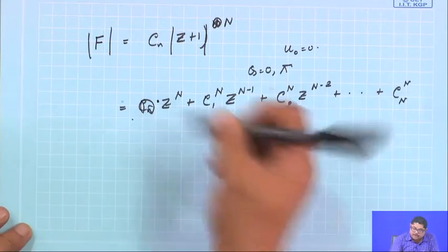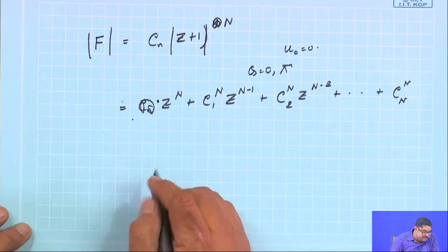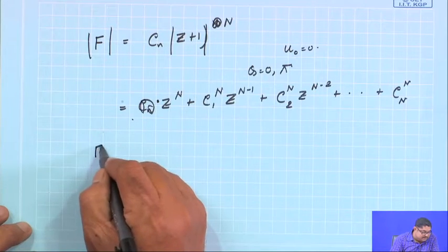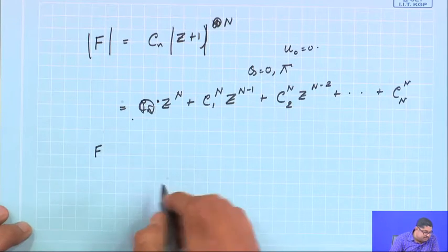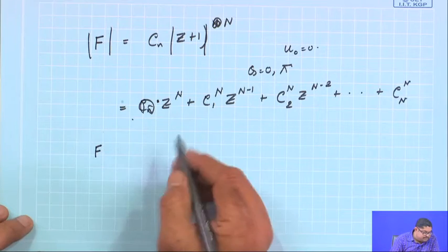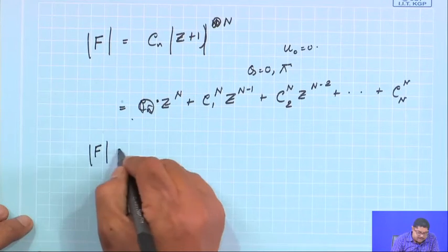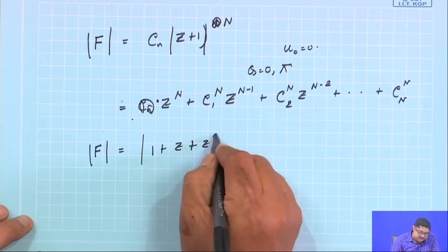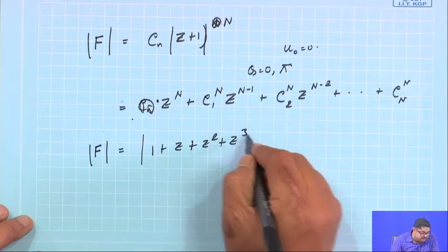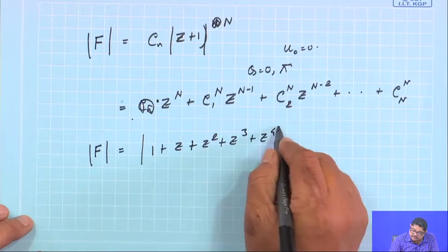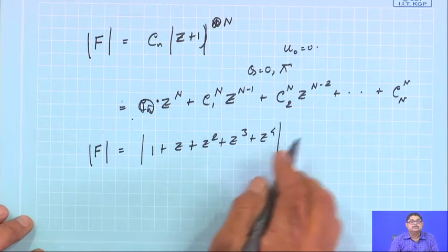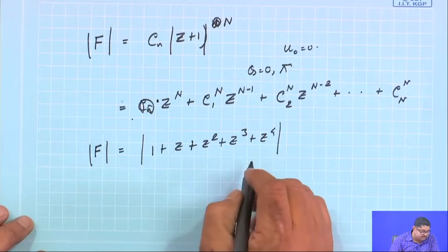Now, consider that instead of these I square these. Suppose an array polynomial is like this, 1 plus z plus z square plus z cube plus z fourth, and I want double zeros at all the zero points of this polynomial.